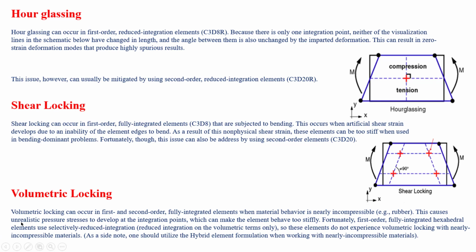This causes unrealistic pressure stresses to develop at the integration point, as if whatever elements you consider are completely incompressible. To avoid this, we have the hybrid element formulation.